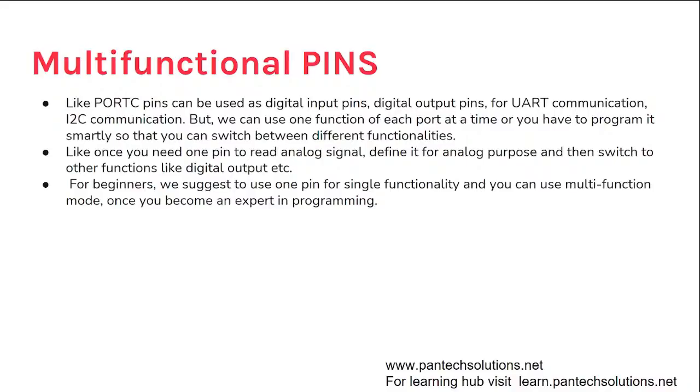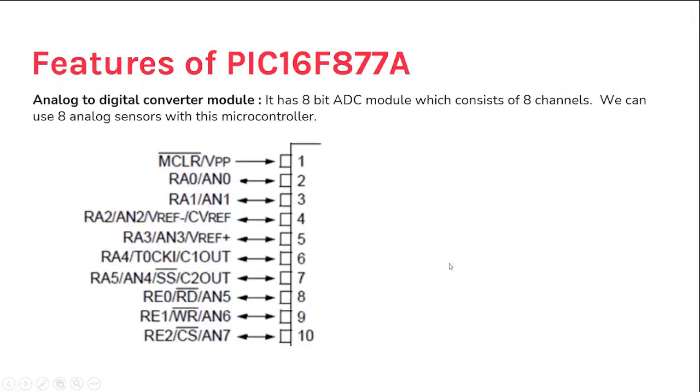These are multiplexed signals. Through the program, you can switch between the different functionalities. If you want to read an analog signal, you can define the pin for analog purposes. If you want to use it as a digital input or output, you can define it for digital read and write. So all these are multifunctional pins.